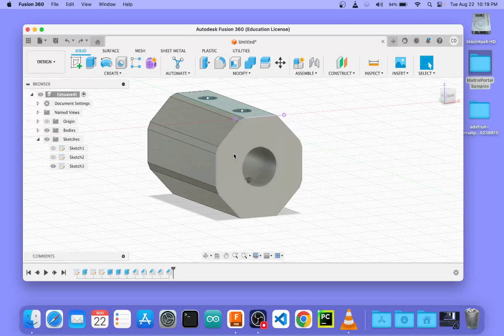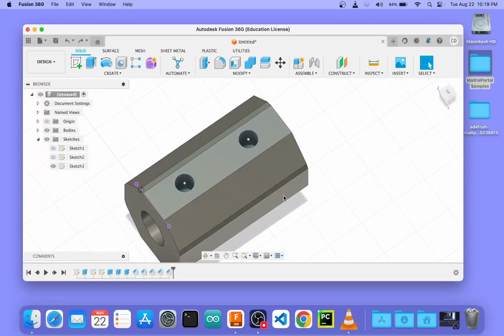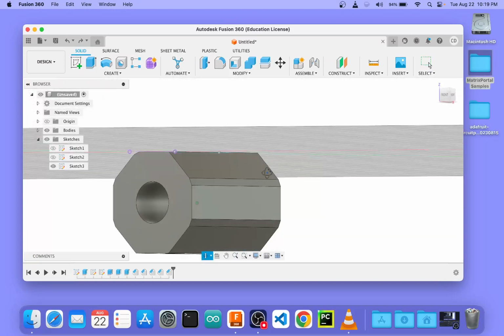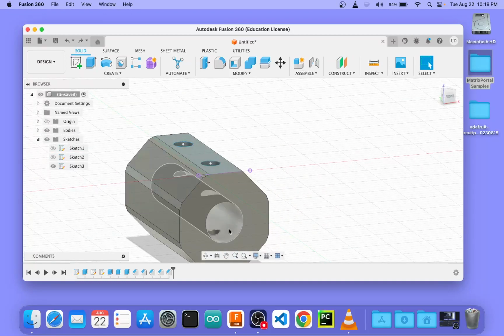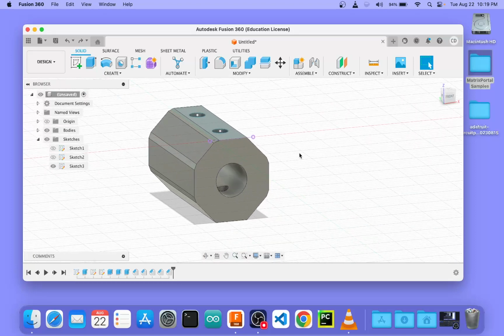But if you are going to individual faces of the objects, if you're making sketches on them, and if you're then using those sketches to do press pulls to either add little bits of material to it or to perform cuts through it or partway through it, that gives you a lot more ability to make interesting things, and we're going to use some of those in the first challenge.